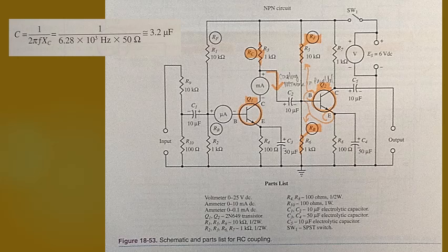Looking at the two-stage amplifier using transistors in figure 18-53, consider the signal voltage at the collector of Q1. There is more than one path for the voltage, and it will always take the easiest path. It can go through RC or through the coupling network that is in parallel. If the network impedance is higher than RC, signal currents will go through RC instead of the next stage. Therefore, the coupling capacitors used in transistor circuits must have values in the range of 8 to 10 microfarads.